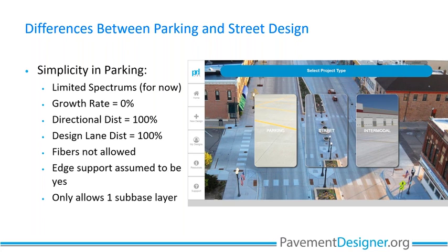Finally, edge support is assumed to be yes within the parking lot design module because most of these slabs within a parking lot will be surrounded by concrete, giving them edge support.